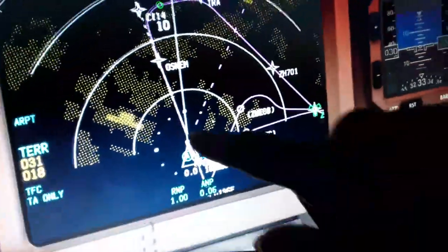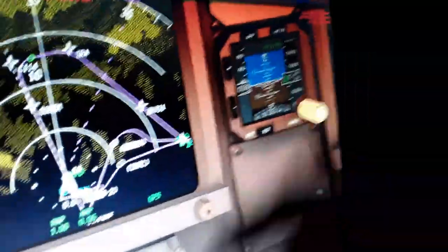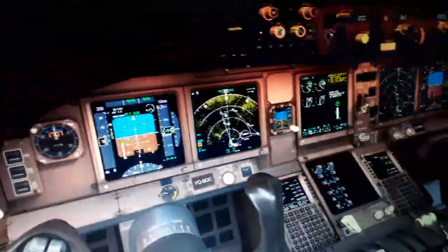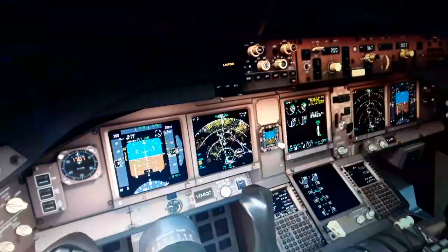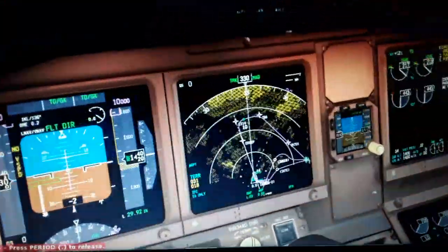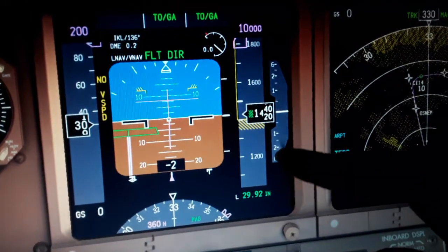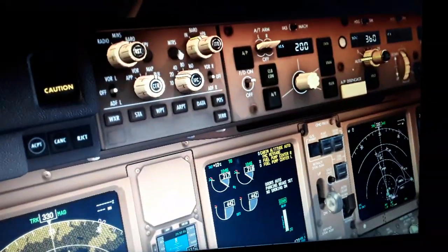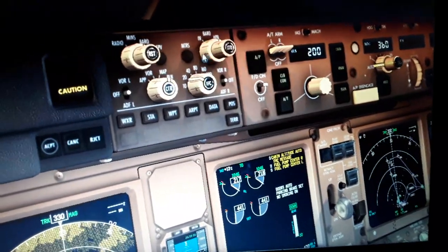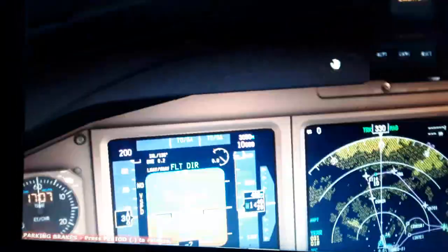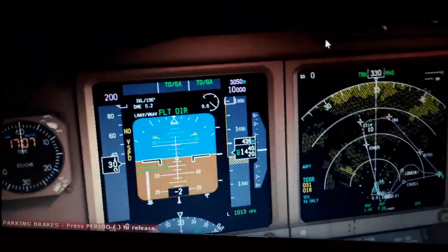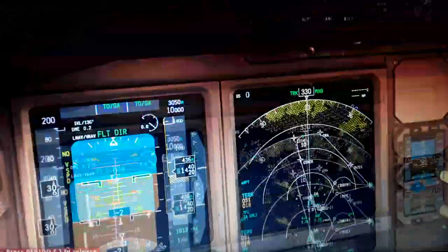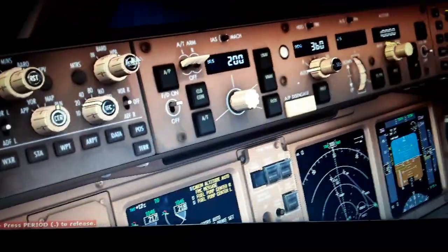You can see the waypoints here. We have the runway for takeoff. We have created already the flight plan. So you can see if we climb, you will see this needle moving up. If we descend, the needle moves down, the flight director and the LSZH localizer. So we can change a few values here. You can have meters, inches of mercury or hectopascals. So you have now also the display of the meters and hectopascals 1013 for here, setting up the barometric altitude,